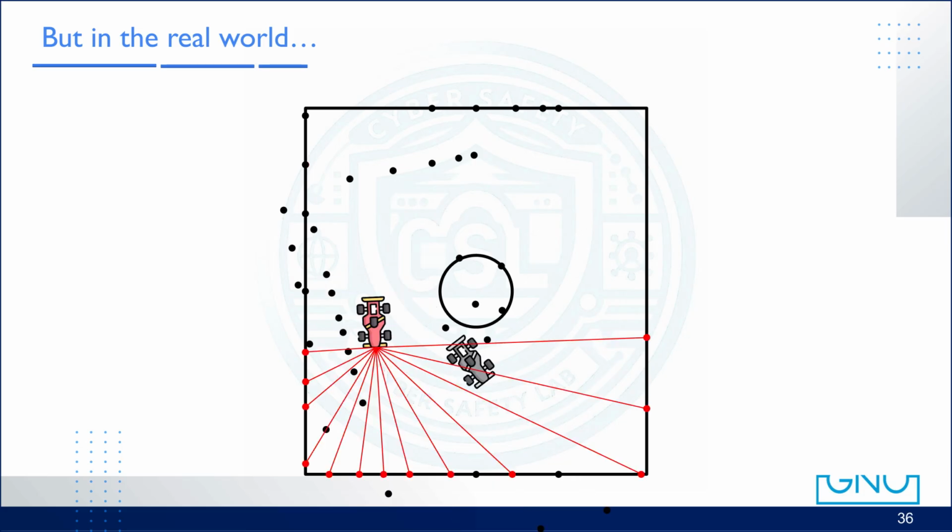Here, the robot believes it is slightly ahead of its true position. Because the odometry has accumulated error, the LiDAR beams are projected into the wrong places. The measurements themselves are mostly correct, but the projection frame is wrong, so every point is misplaced. This is the moment the map begins to drift away from reality.